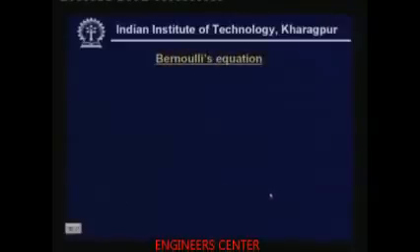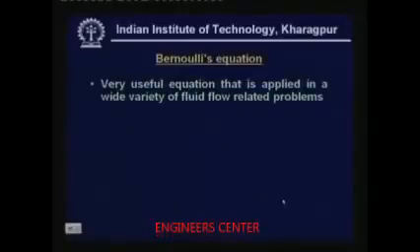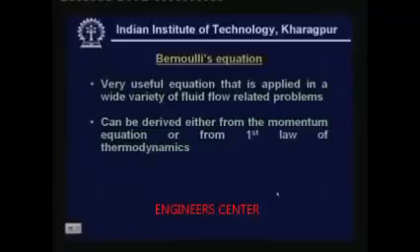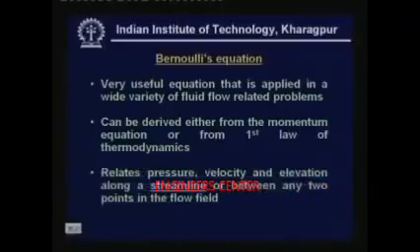Now let us look at one of the very important equations called Bernoulli's equation. This equation is applied in a wide variety of fluid flow related problems, and it can be derived either from the momentum equation or from the first law of thermodynamics. That means either you can use the momentum equation or basically the Euler's equation, or you can also derive the same equation from first law of thermodynamics or conservation of energy equation. And this equation in simple terms relates pressure, velocity and elevation along a streamline, or between any 2 points in the flow field.